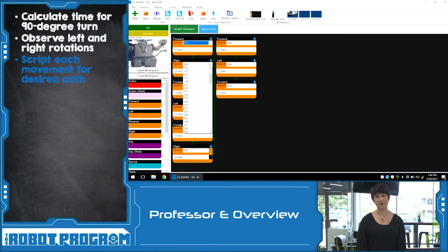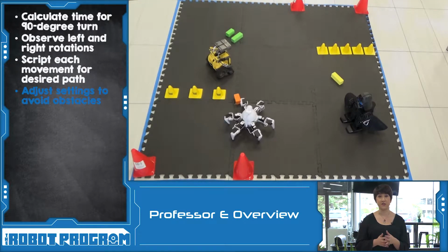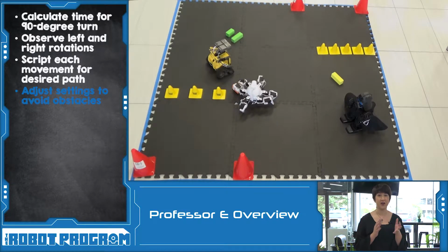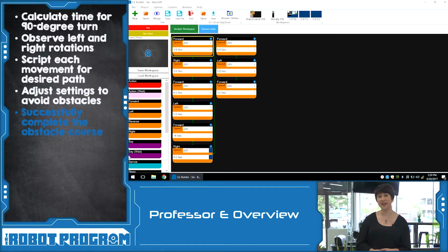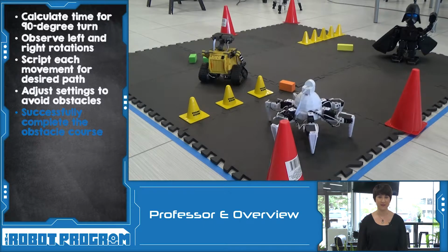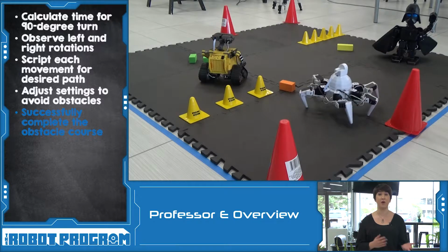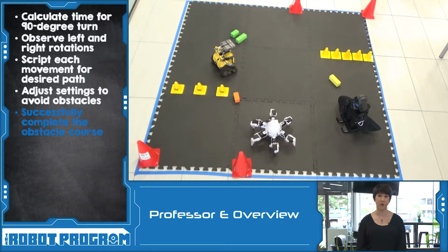Use the green Start button to run your code and tweak any of the values that might need to be adjusted. These trial runs let you see if your robot is not turning as much as you want it to, or if it's running into an obstacle just at the very end, or if you just need to change things a little bit. Once you have the speed settings and time settings exactly how you want them, you can run the entire obstacle course. This knowledge will be useful in future activities if you need your robot to get around an obstacle, or if you just want to execute movement in a very specific way.